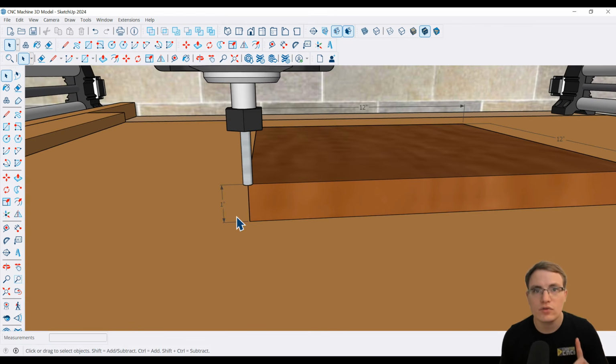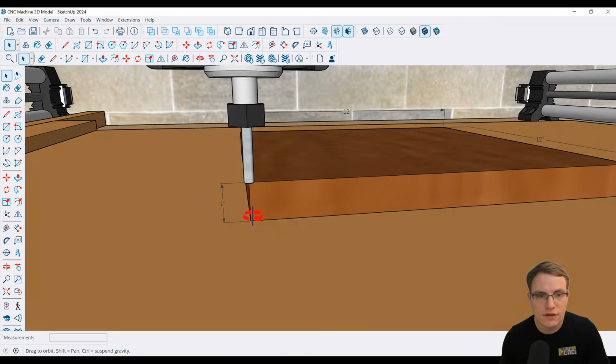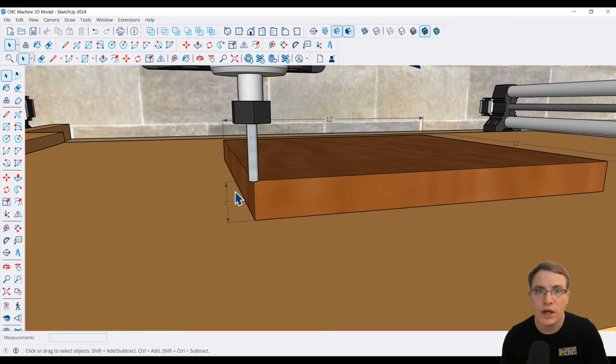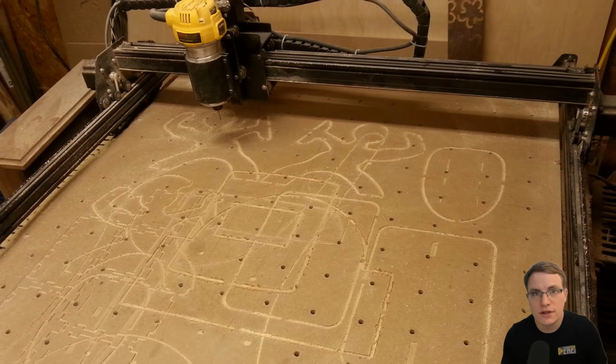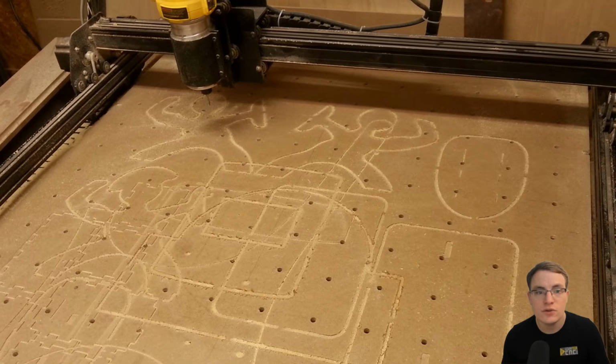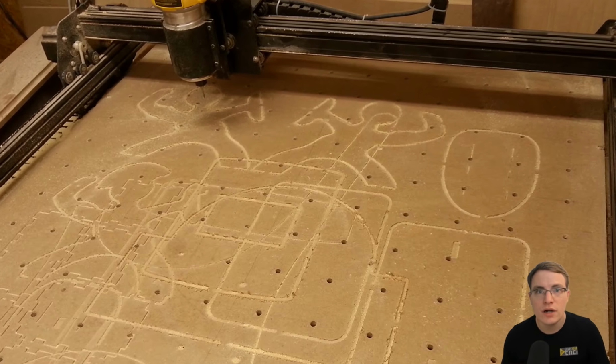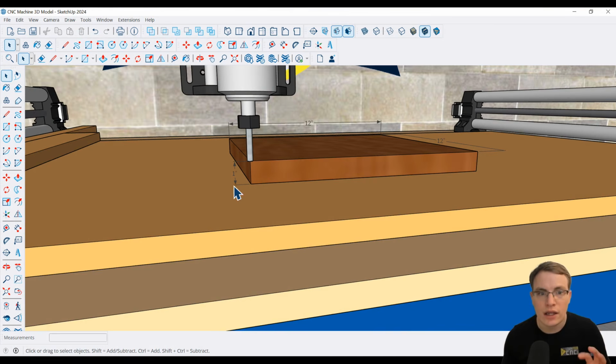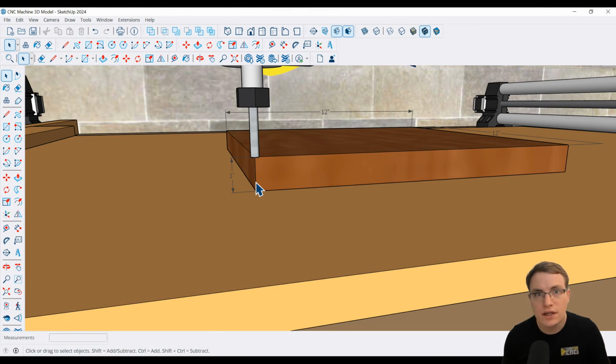The thickness is the most critical in most cases to get your toolpath correct, because if this material thickness is different from what you enter into Vectric, that will make a big difference whether or not your toolpaths will cut correctly. You may have even experienced this if you've been using CNCs for a while. Your machine actually cuts into your spoil board below your material, and a lot of times that is caused by either having the incorrect material thickness set up or having your zero not zeroed correctly on your machine. So keep that in mind whenever you're working with material.